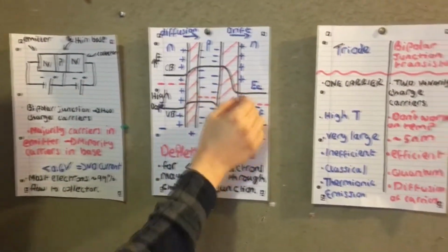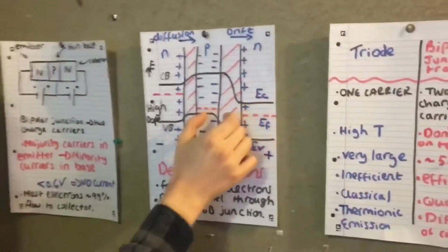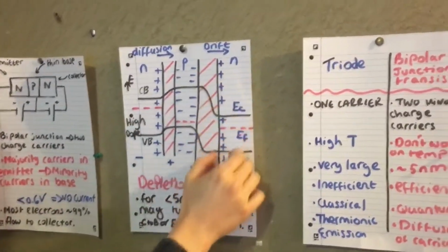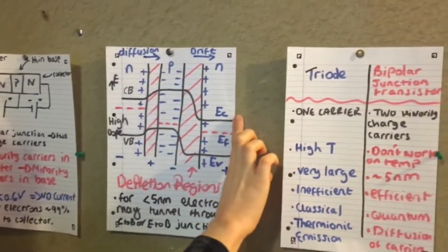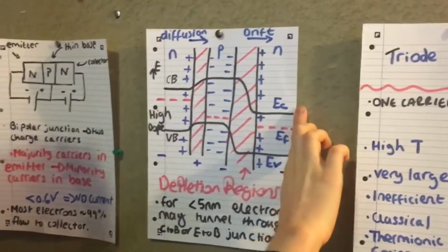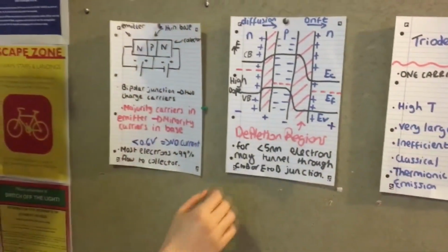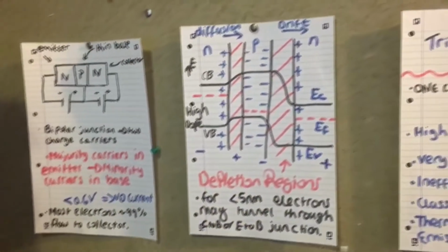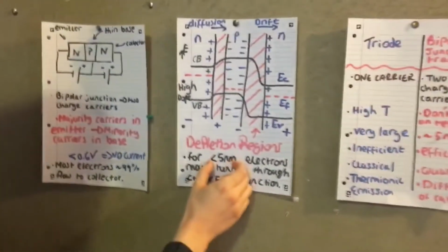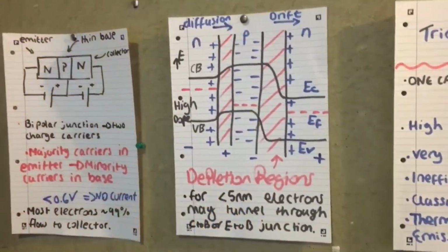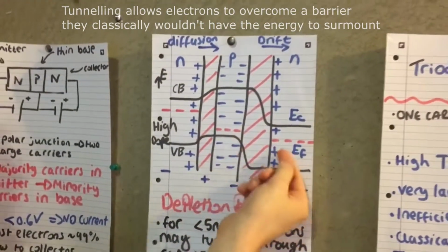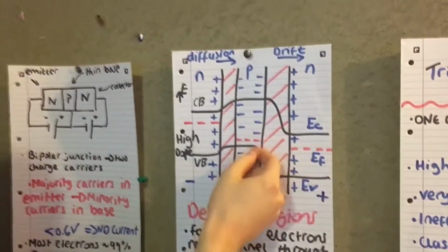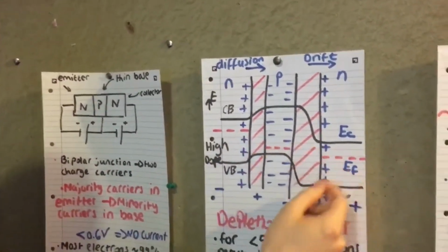The electrons are aided in moving across this depletion region by the ionized dopants on this side of the depletion region, and the positive anode connected to this n-type. Note that this transistor will only work down to a certain size, which is around 5 nanometers, because at this point the electrons will start quantum tunneling through the depletion regions, which will cause reverse current through this section and forward current through this section without control through the base.